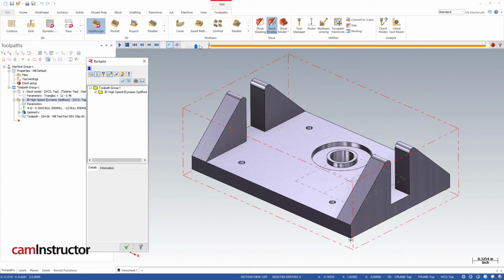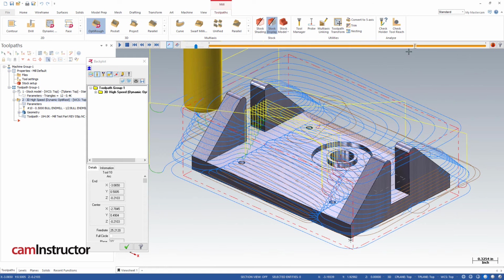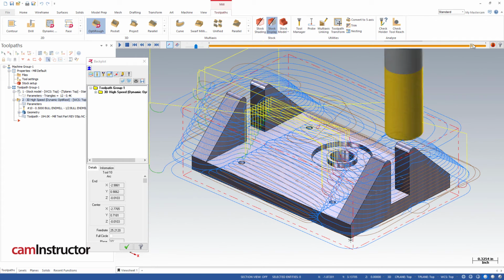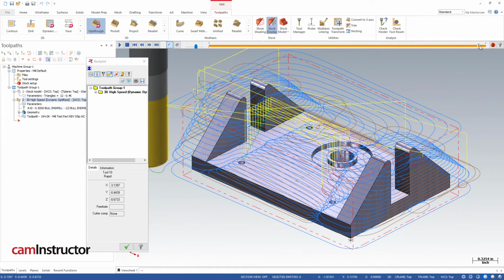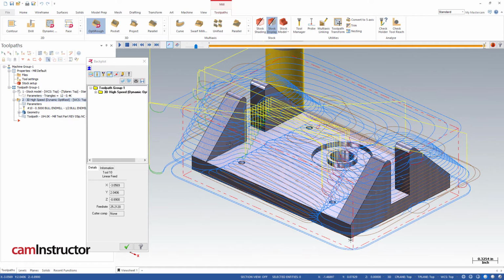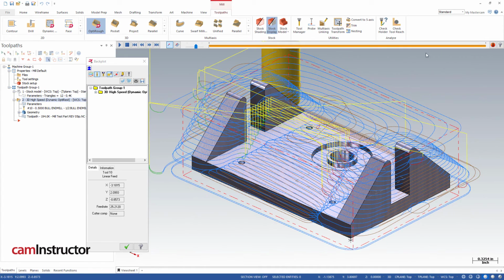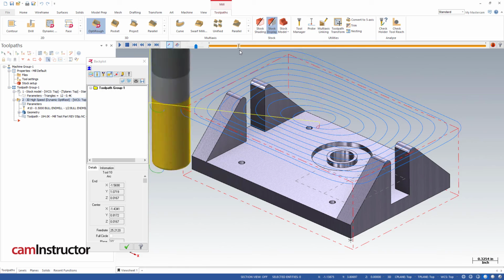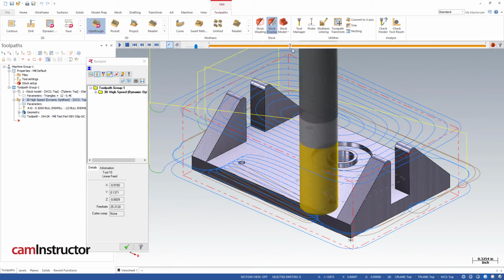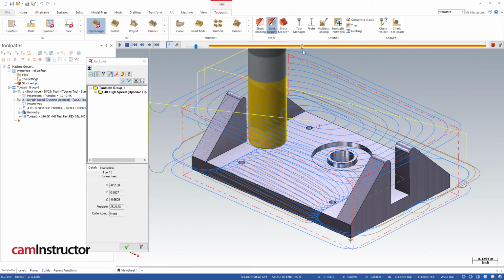So back into this, analyzing the toolpath. Notice we've got this cut going around the bottom of the part. I did notice at the very end, right here, it's doing that same toolpath again, but just a fraction lower for some reason. So that's not great either. So that's wasted tool motion. And the very, very top, that's all wasted tool motion. So we got two things to fix up. And I think everything else looks good.